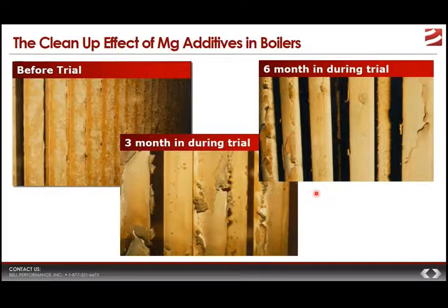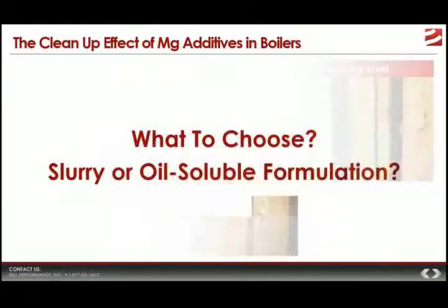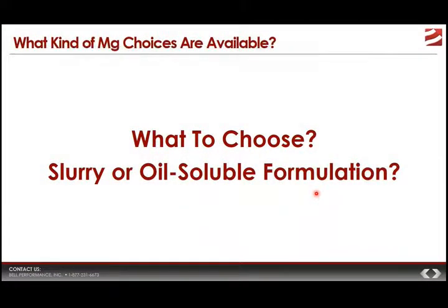So we can see pretty clearly that magnesium additives do a number of good things for fuel oil users. But we have to consider the fact that not all forms of magnesium are created equal. Generally speaking, you have two major forms of magnesium to choose from. You have a slurry or you have an oil-soluble formulation. Let's consider both of these and look at some of their pros and cons.